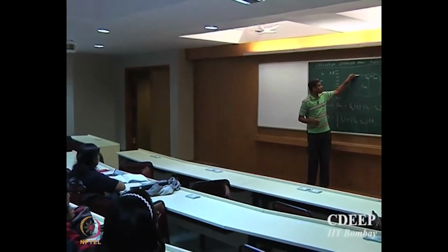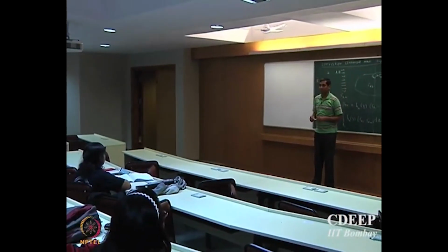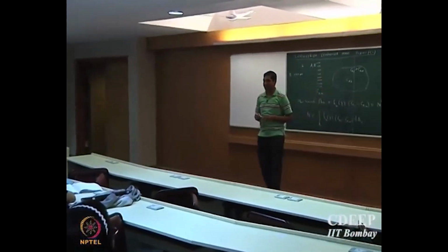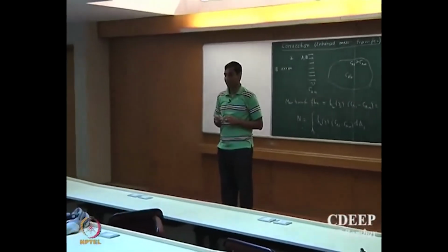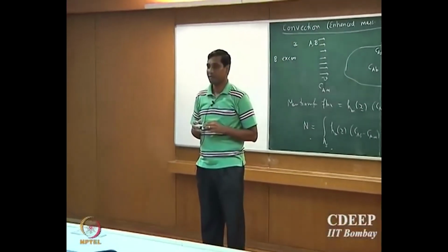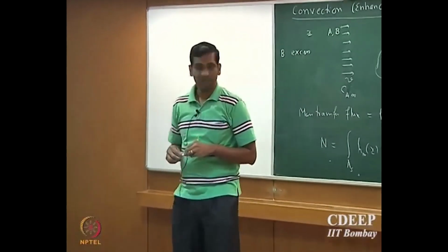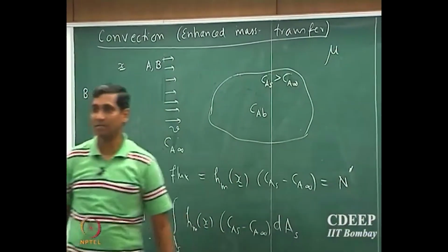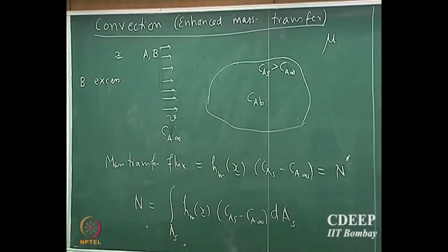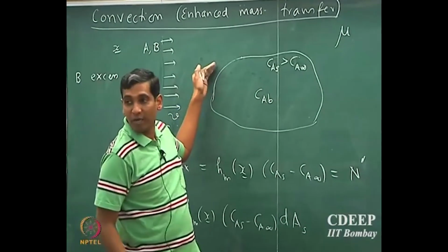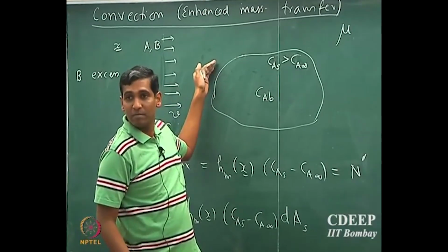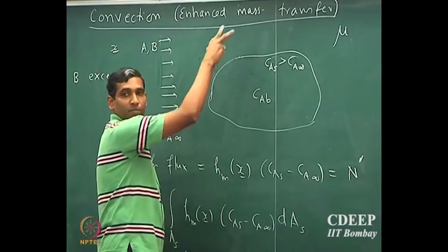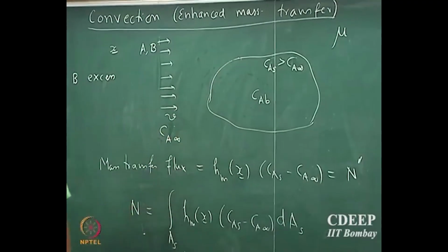What matches here is not the exact mass transport rate with respect to bulk concentration and the mass transport rate outside. That's not the conserved property. What's the conserved property here? Have you heard of chemical potential? Must have heard of chemical potential, right? So what you have to match at the boundary is actually an equilibrium between the species which is present in the gas phase and the species which is present in the bulk phase.